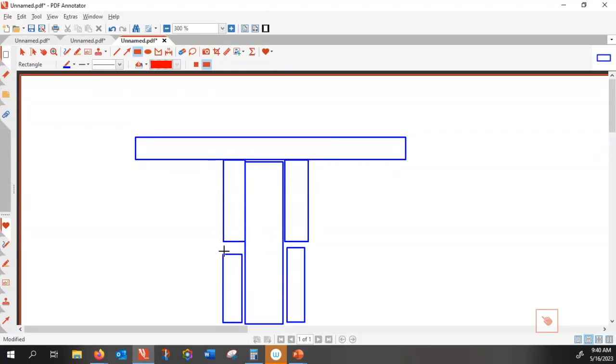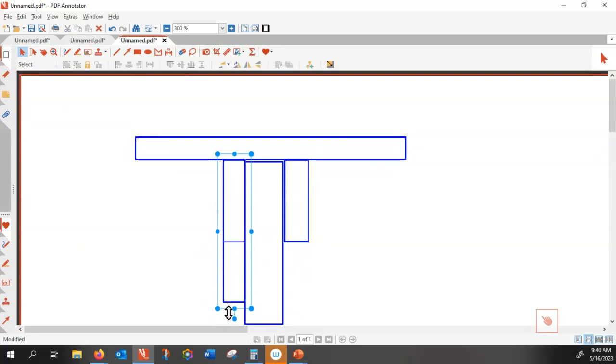So if they wanted to fabricate something, it was much more reasonable to join this and get away with that variation. You know what I mean? Because that point where you have a smaller b, b goes to the denominator. The smaller the b, the larger the shearing stress. That means you want to avoid that.